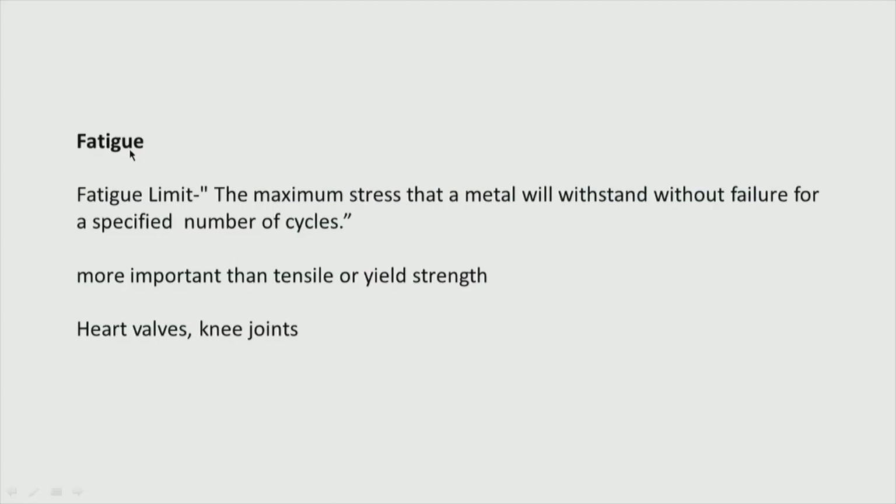Fatigue is another important property which comes in of course even in non-metals. The maximum stress that a metal will withstand without failure for a specified number of cycles. For example, if you have heart valves, it keeps on moving, opening, moving, opening. So that is how many times we can do that. It is more important than tensile or yield strength, because heart valves, knee joints, all these undergo a lot of fatigue. Okay. So that is more important rather than the strength.